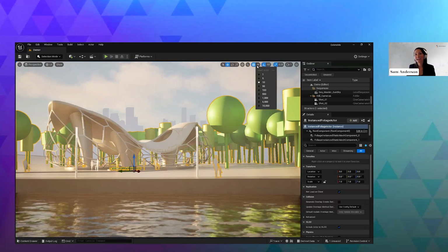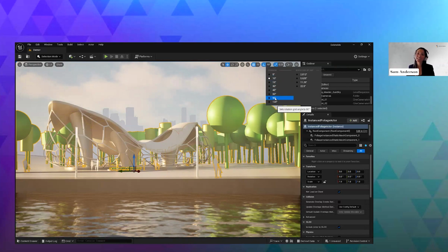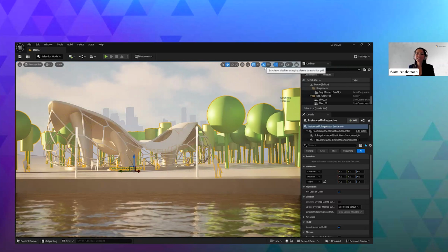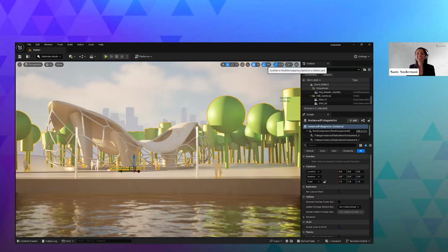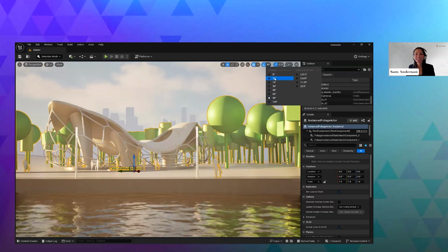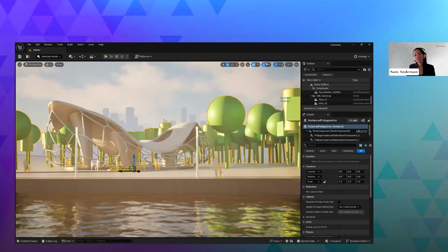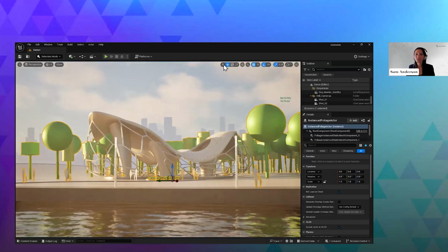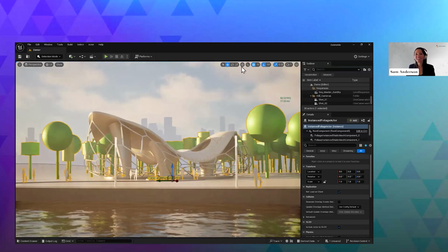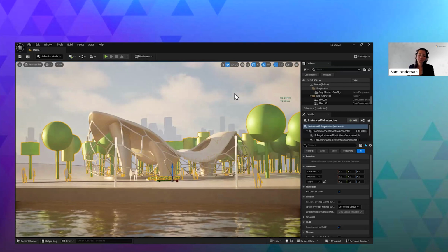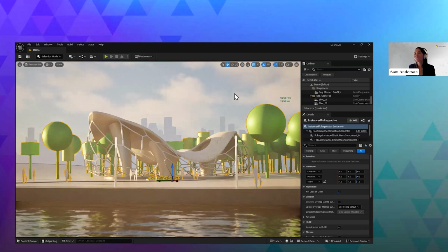This essentially allows you to snap to 10 points down the grid, or if you are rotating something, like furniture that you just want to rotate 90 degrees each side, you can select this 90 degrees, and it's going to make sure that it snaps easily to that 90 degrees. So I'll go ahead and select that back to 10. These are tools here for you that you can play around with and use when you are working and developing inside of Unreal Engine.